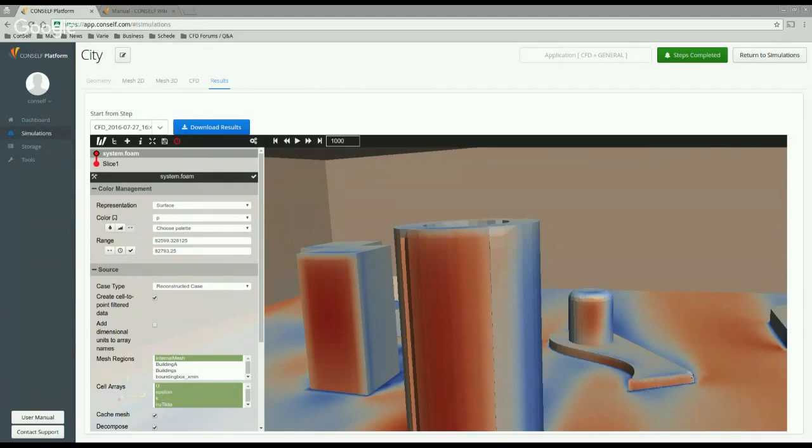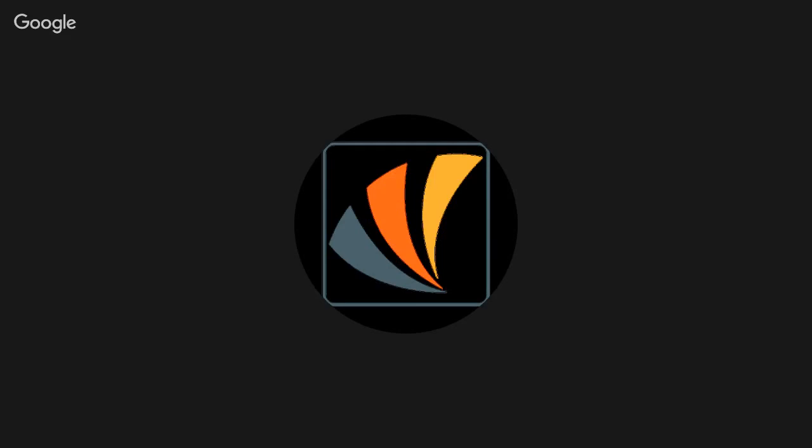It's a very simple file, so I'm going to open it. It's inside the result folder, sampling surfaces. You choose the iteration you want to obtain results, and you will see a p-walls interpolated .raw, and that's our file that will show you a very simple way to perform your load evaluation.